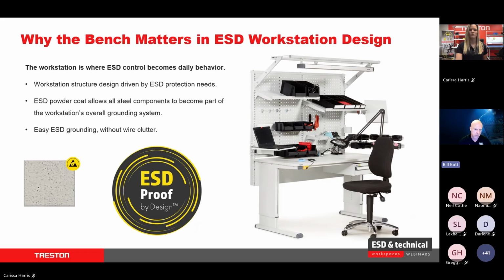The large number of accessories that they have that support this are inherently ESD protective. So it's not a decision-making process for you or your employees when they place things down there. There's no labeling involved. I don't need to say this is not an ESD shelf. I mean, that's what we contend with a lot of times. We find out, and we'll talk about that in a minute, the shelving isn't labeled, but people don't know that. They just put things down because it's at an ESD protected workstation. The labeling gets ripped off. So those things happen, and this solution here solves a lot of those issues.